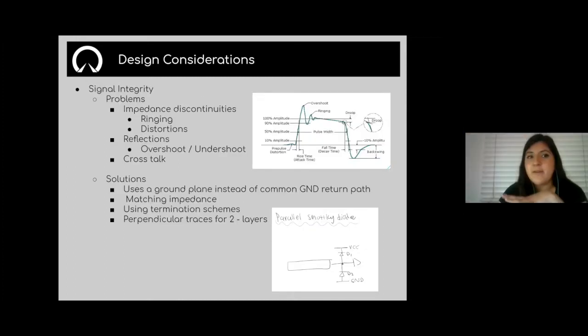All right, some other pretty big considerations are signal integrity and thermal optimization. But for the first one, signal integrity, that just refers to ensuring a quality transmission of electric signals. So you could have some problems with signal integrity wherever you have vias, wherever you have more than 2 signals branching, where you have a signal plane that splits, any high-speed signals, or mismatched impedances. So this could also result in a lot of problems.